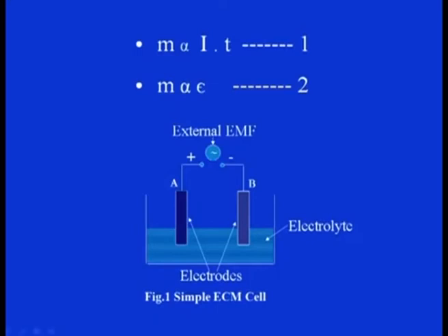A simple ECM cell is shown here on the screen, where this is the electrolyte and these two, A and B, are the two electrodes, connected through some wiring to a voltage source. Then the current will pass through this and the electrochemical action will start here, and dissolution of the material will take place.